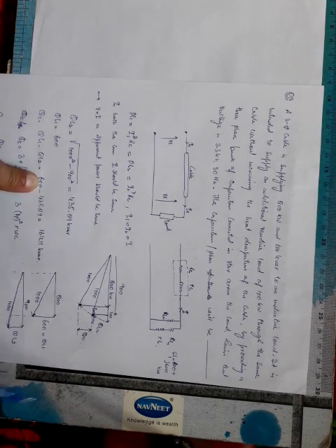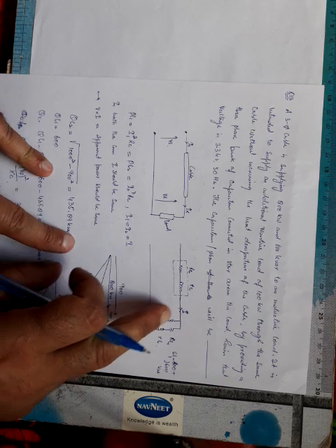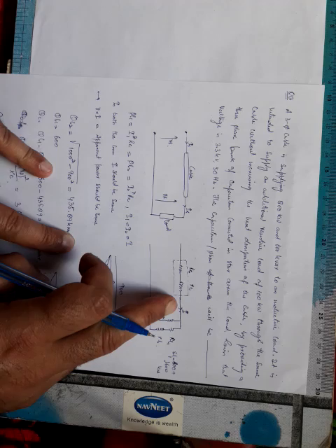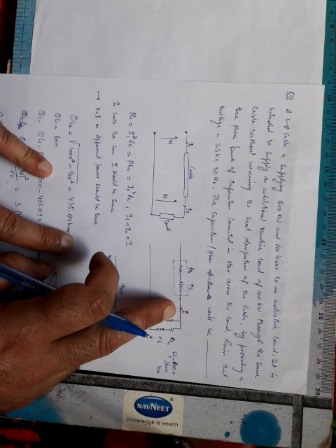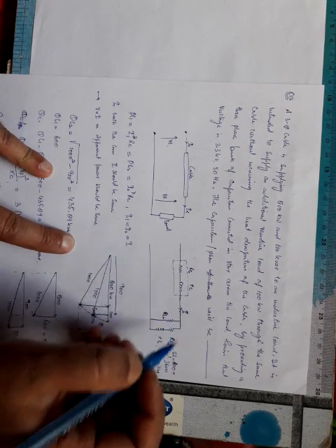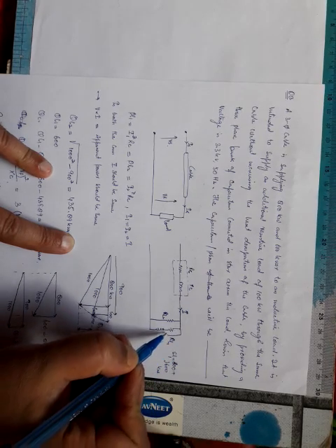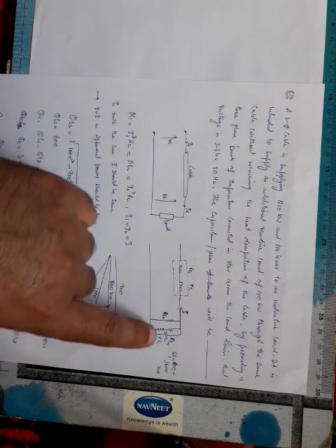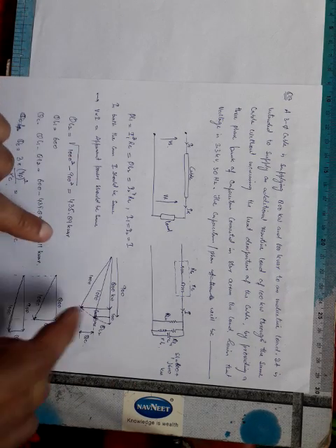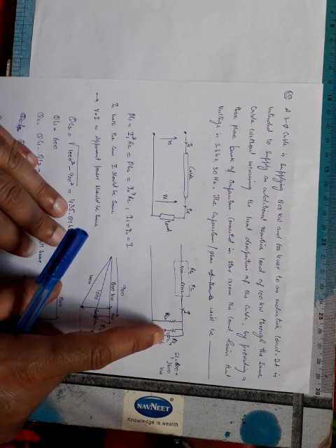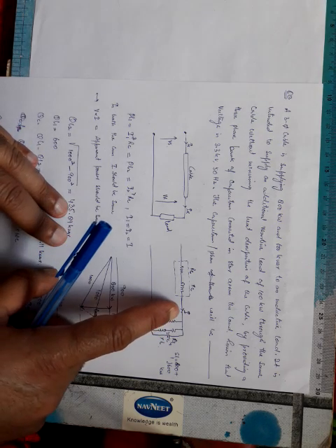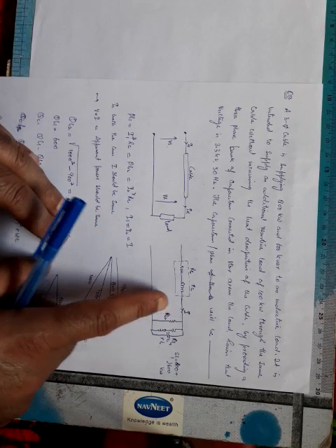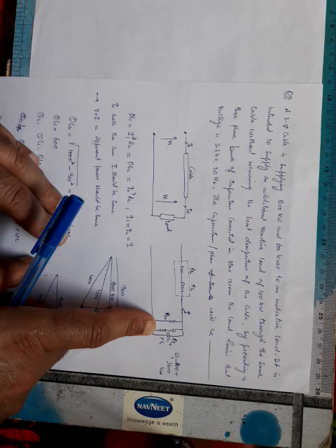But in this circuit, it is not possible. You can see that this I should be equal to this current plus this current. Before connecting this, I assume this to be I, and after connecting this, I am saying that this is again I. But this is only possible when I use a capacitor over here, this C. So I have to calculate this C so that before connecting this R and after connecting this R and C in parallel to this circuit, the current remains the same, because this will definitely be a lagging current, as this is an inductive circuit.